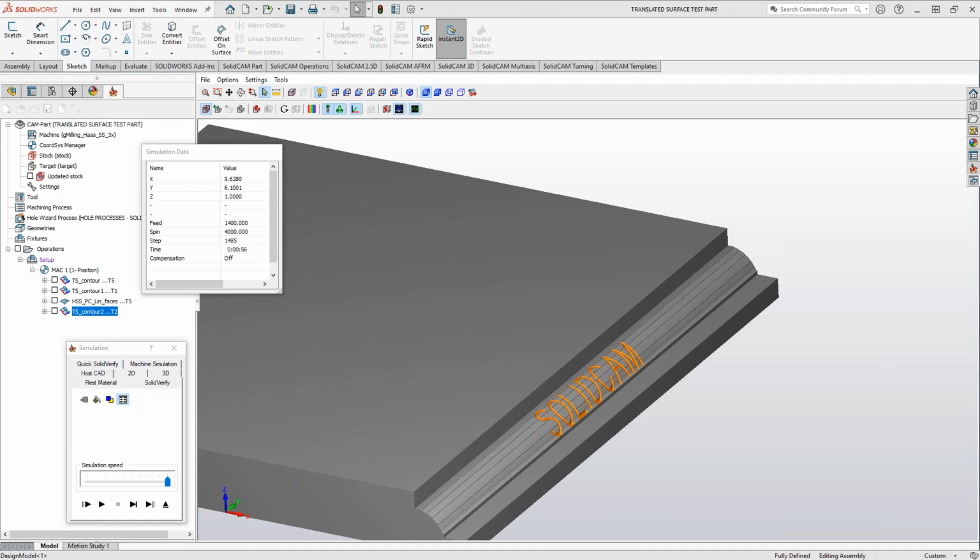Very similar to what we talked about yesterday with the contour 5-axis in the same scenario. Maybe you're trying to generate a 5-axis toolpath where the surfaces are not helping you, you don't have any 3D geometry that'll help, and you're stuck just using sketches. Here, you could do very similar stuff that you would do with HSS that relies on surfacing, but here you're using just sketches. So it's kind of like Kevin said a second ago.